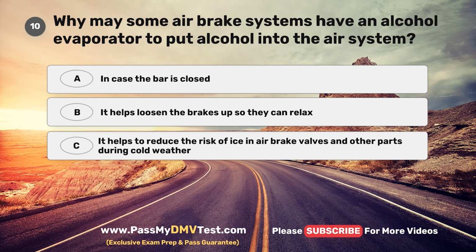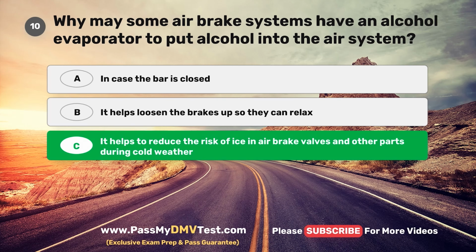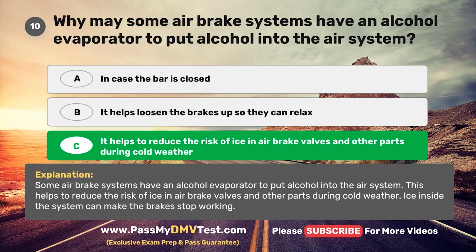Question 10. Why may some air brake systems have an alcohol evaporator to put alcohol into the air system? A. In case the bar is closed. B. It helps loosen the brakes up so they can relax. C. It helps to reduce the risk of ice in air brake valves and other parts during cold weather. The correct answer is C. Some air brake systems have an alcohol evaporator to put alcohol into the air system. This helps to reduce the risk of ice in air brake valves and other parts during cold weather. Ice inside the system can make the brakes stop working.